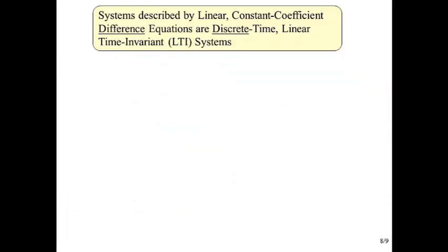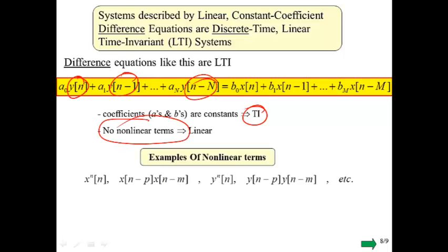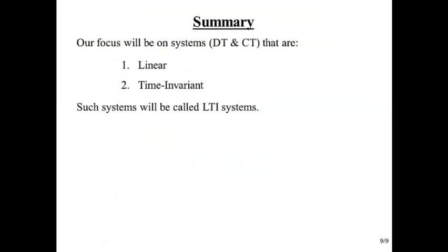Same thing for difference equations, except here, instead of having derivatives, it's just different shifted amounts of the input. Again, the coefficients have to be constant in order to be time invariant, and we can have no nonlinear terms. So in a similar kind of way, no powers, no cross products. You can't have an x times a y, no square roots involved or anything like that.